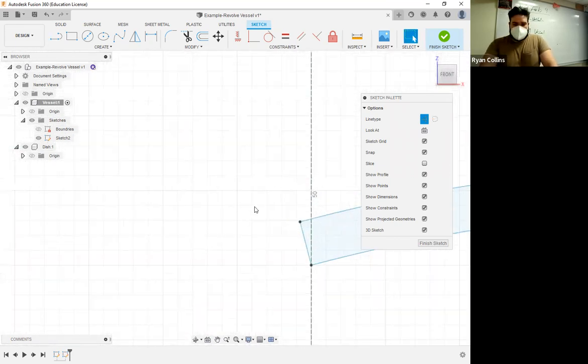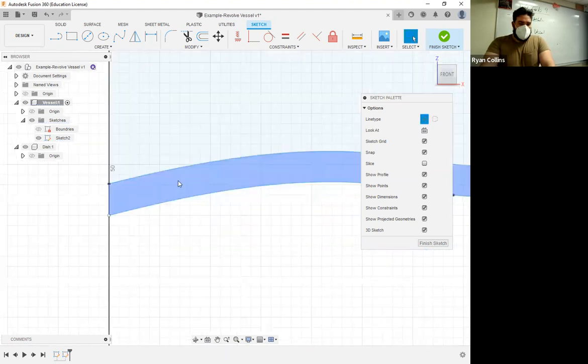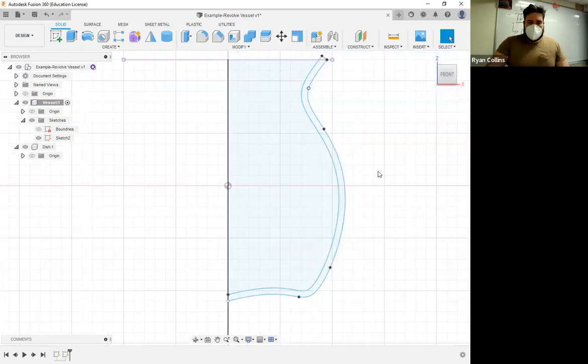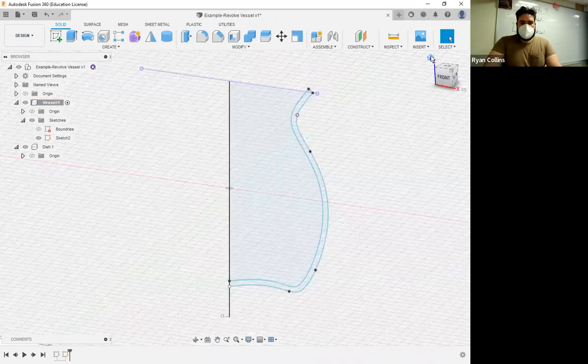Now when I zoom in, use my trim tool. I can chop those parts out. Now that does show up, but because it's a construction line, it doesn't complete the sketch. So if I do in fact want that to be my other line, I could draw that in manually, or I can just use the line that's already there. So I can change that back from a construction line to a regular line. Now my profile is closed. Okay. Zoom back out, go back to perspective.